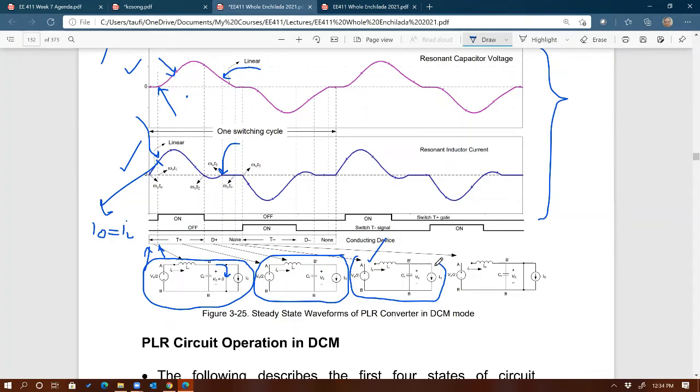See that? So the capacitor is not fully discharged, therefore this forces the output current to flow through the cap, discharging this capacitor with constant current, which means the rate of the discharging voltage on that capacitor will be linear, not a sine wave.